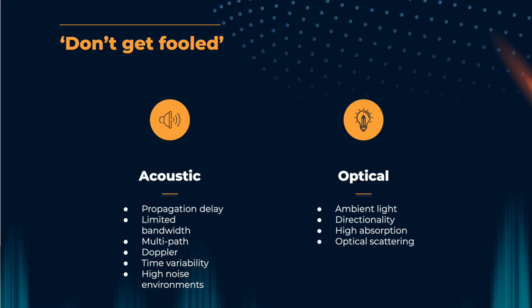It's especially true in the case of acoustics, because the signals that we are transmitting, as you heard, are very, very long. And the pool walls are very, very close. So the reflections and the direct arrivals come at the same time or very close to each other and interfere. So you need to play with your power level, how loud you are transmitting. And you probably need to also play with the length of the transmission, which I will not go into the details of now, before you get it right. Okay, that's number one. The second is propagation delay.